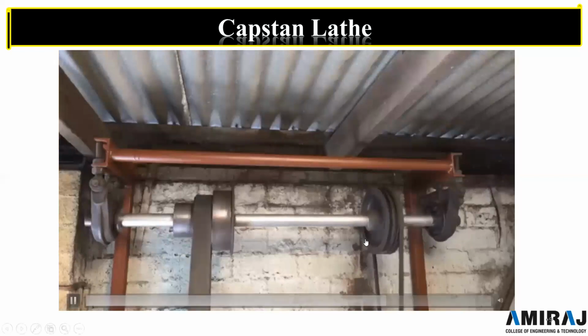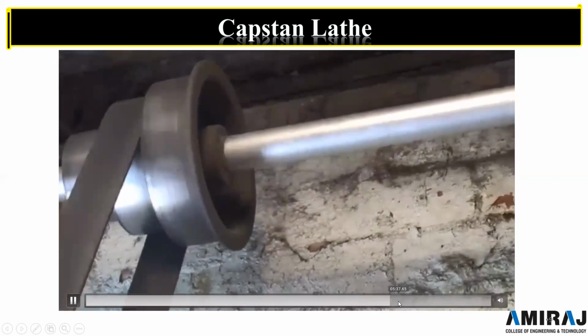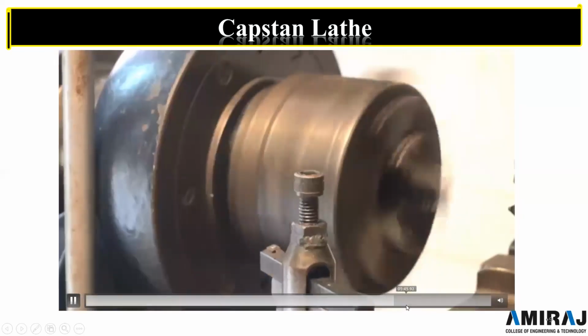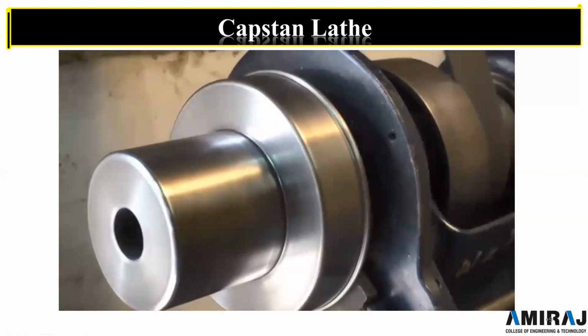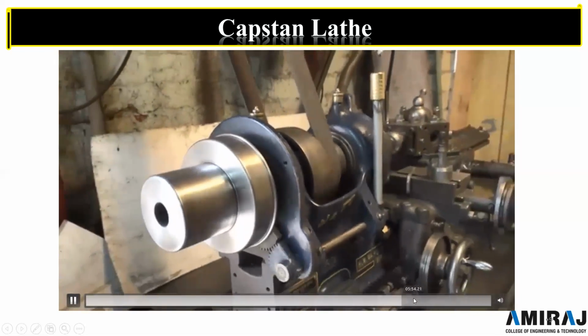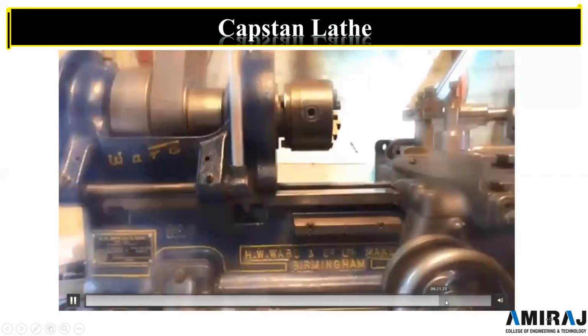This is how the belt drive engagement and disengagement is done. By the 1930s, gear-driven Capstan lathes were available, but belt drive lathes were still being produced because many factories still used overhead line shafts. In the factory where this lathe came from, there was an overhead line shaft driving multiple machines. I think the overhead shaft and pulleys that I have were an intermediate shaft driven off the combination motor and pulley arrangement with the lathe.